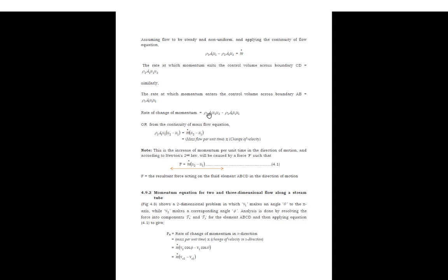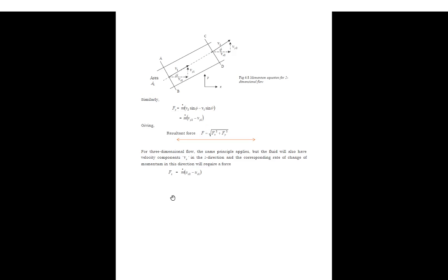When you summarize this, since the density is the same, the cross-section area is the same if you add the continuity, and the U is the same. So at this point, the mass rate times the change in velocity gives the result. This formula suits the second law of motion, which says that the rate of change of momentum is directly proportional to the force applied, implying that the force is equal to the rate of change of momentum. So this is what we are basically having.